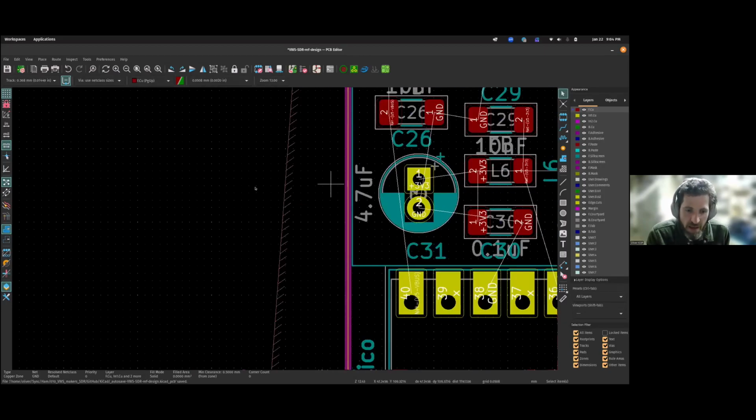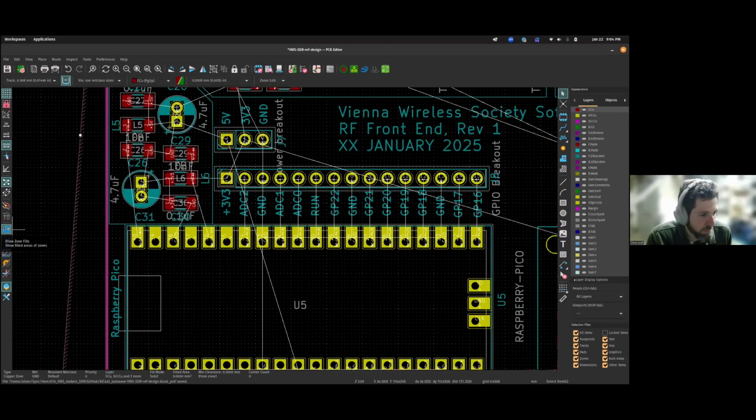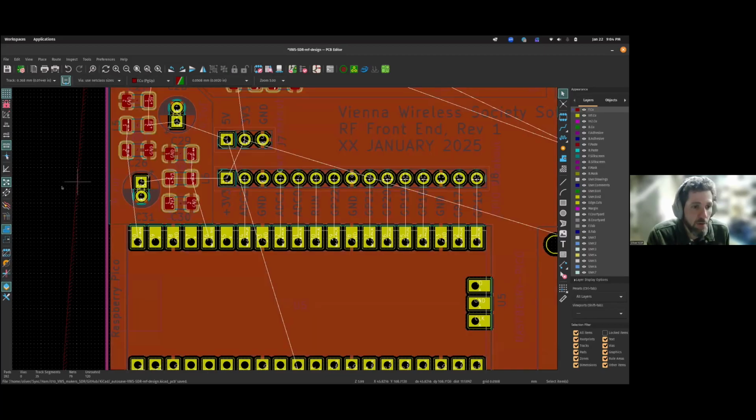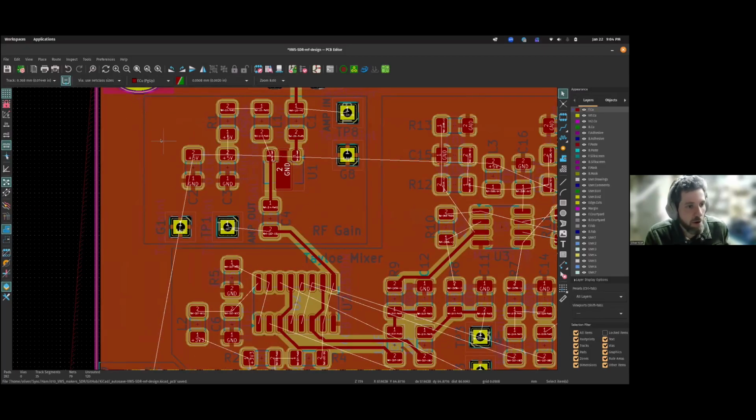You'll see it's got this funny stripy edge to tell you what it is. And if I hit the B key on the keyboard, it will now do the logic of drawing this ground plane all over the PCB. So if I hit the B key, it will build the filled zone, and now I can see that it has filled copper in on the top layer. Everywhere where there isn't already a trace or a footprint, it has now filled in with copper, and it's observed whatever the distance rule this particular net had for how far it gets up to the edge of that particular trace.